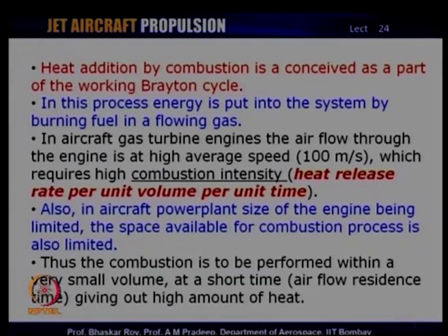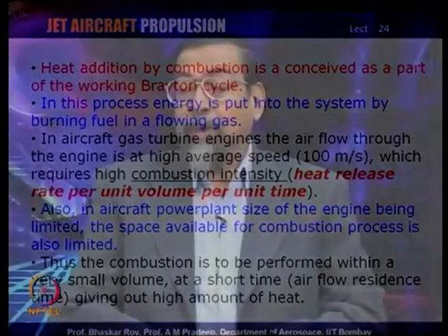So, in a fraction of a second, you have to release the heat that is available from burning of the fuel. So, you do have very small amount of time and very small amount of space to complete the process of combustion. And this is one of the challenges of designing the combustion chamber, that in a very small space and of course, in a very small time, you have to complete the process of combustion.